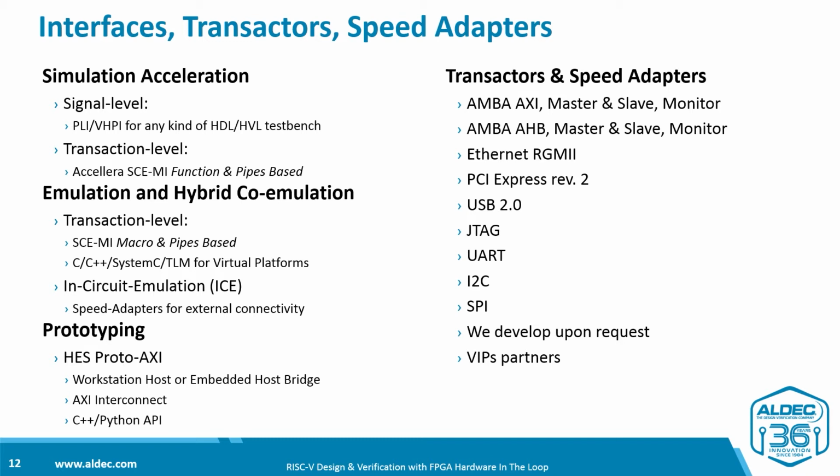Emulation and hybrid co-emulation are supported by a transaction-level interface, which is compliant with the Accellera SCE-MI standard. Additionally, Aldec provides SystemC and TLM wrappers to facilitate connection with popular virtual platforms. In-circuit emulation, which often requires connection with external devices running at higher clock rates, is supported by the speed adapter dedicated features in DVM, and also by support of multiple clock domains.